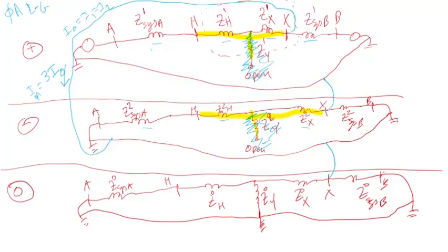So here, let's call this current that flows here I1H, the high voltage current in the positive sequence network. And since here it's not the same current, we'll just call this I1X, the positive sequence current that flows through the low voltage. And we'll do the same thing here. It's I2H, and this, no, sorry, this one, it will flow here basically, I2X.